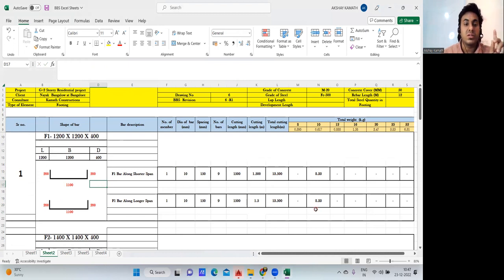So we have taken two cases. One case where the bend deduction has to be applied, and also you don't have to take the complete 2/3. Here, no bend deduction, but you have to take 2/3. In this way, there may be another company which says that, like we did previously, you don't have to apply bend deduction, and you don't have to take the complete two-third depth. Accordingly, you can work it out, based on what the companies follow, right?